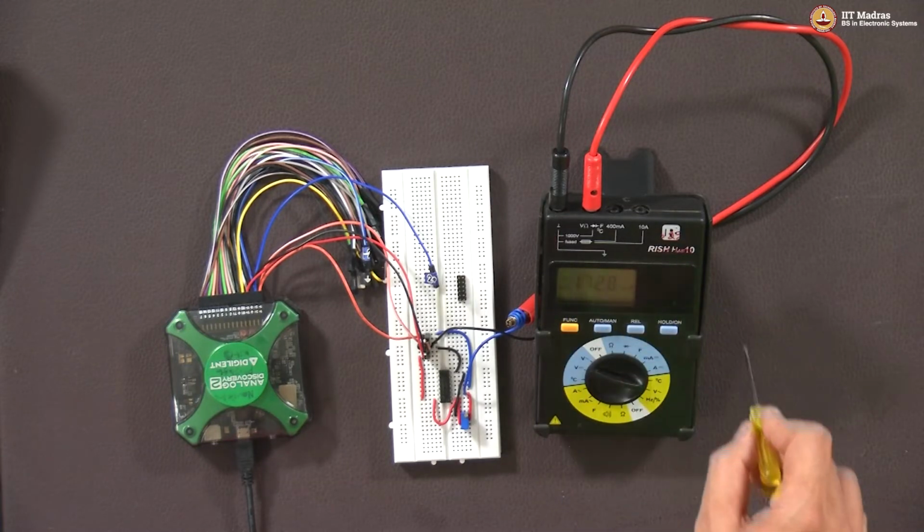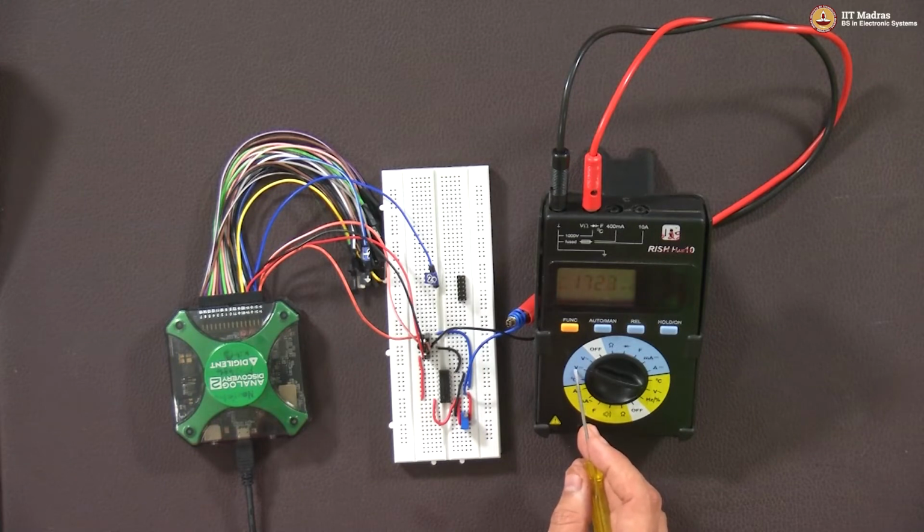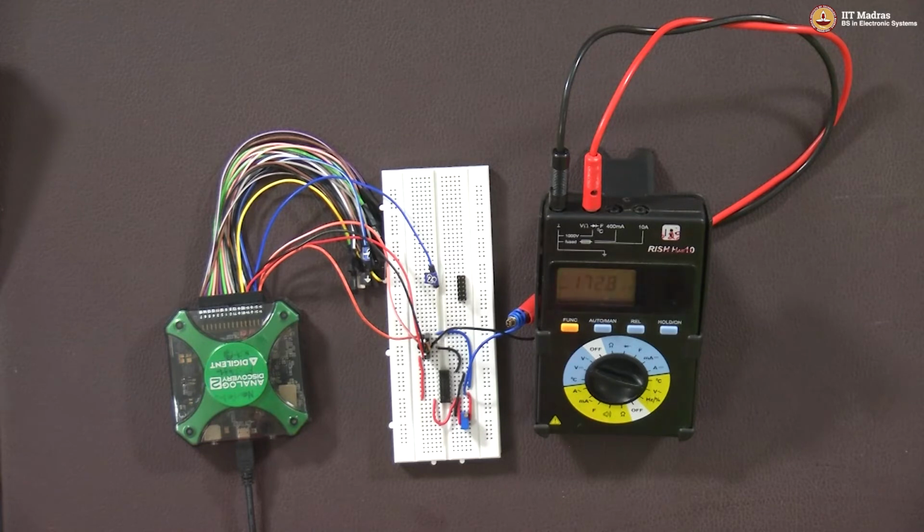Now I have the multimeter here, which has been configured to actually read out a DC voltage, as you can see from this setting here, right. In fact, you can already see that it is reading some value of 172.7 millivolt. So what we are going to do now is vary this screw here, tune the screw and look at the voltage that is appearing on this multimeter, and the output voltage is going to be available through this kit on channel A of the oscilloscope, right.